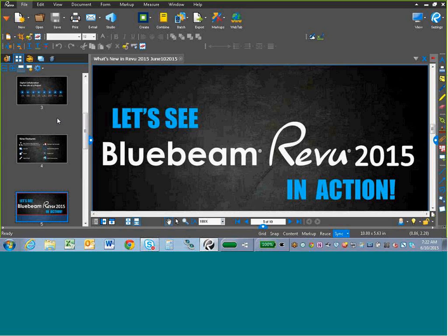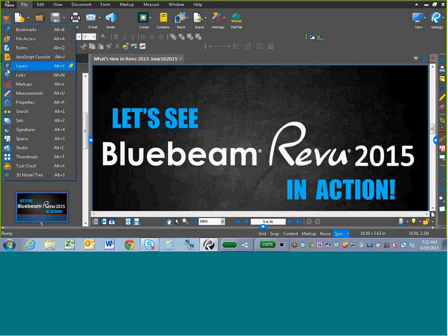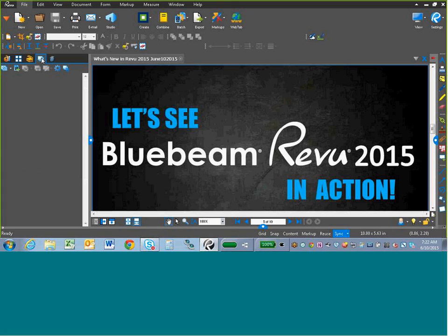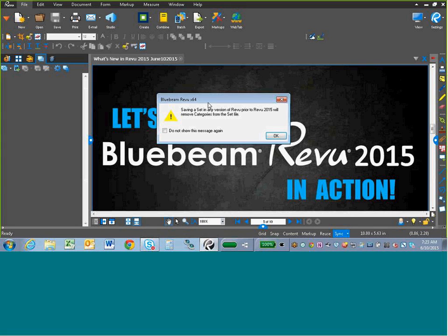When you first create a set in Revu 2015, you are going to get a warning. So let's just go over here. I'm going to go to my tab Access. Again, this is really great because I work with the product every day and don't remember where all of those key features are. And we are going to go ahead and add files to a set. Now, as I mentioned, when you start a set in Revu 2015, you will get this notification. Saving a set in any version of Revu prior to 2015 will remove the categories from the set file.